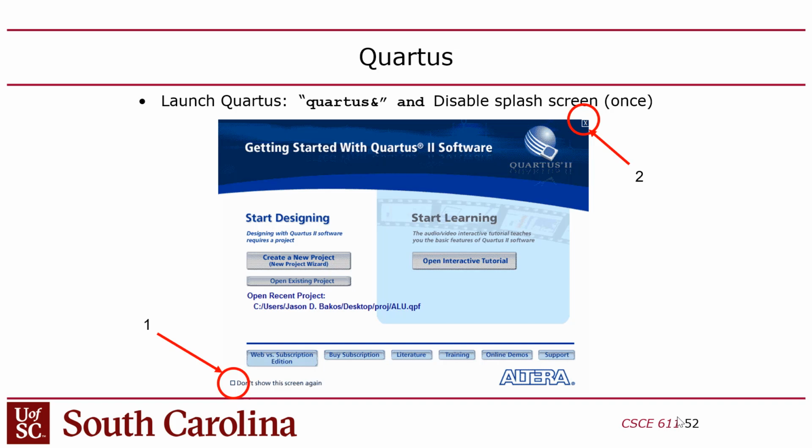And that one was routed to one of the LEDs on the board, right? But you don't want to have to remember those names and those numbers. You just want to say LED 5, right? And so the pin mappings are what sets up that correspondence. So that's something else you have to set up. And inevitably, if you guys do this manually, you'll forget to do that pin mapping. And so if you don't have a pin mapping and you synthesize your design, it will randomly connect pins from your top level design to pins on the board. So it'll glitch and freak out. The board will do this weird glitchy, flashy thing. So you don't want that. So we just kind of set it up for you.